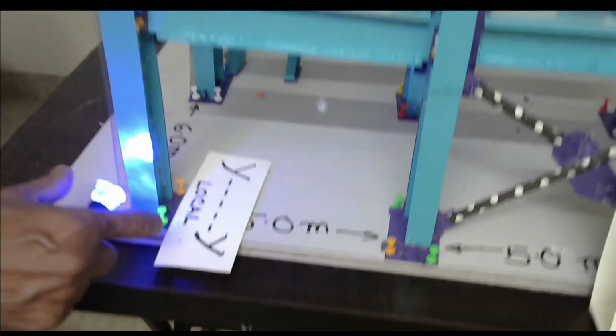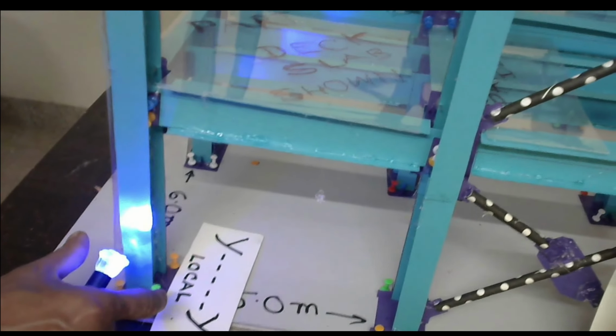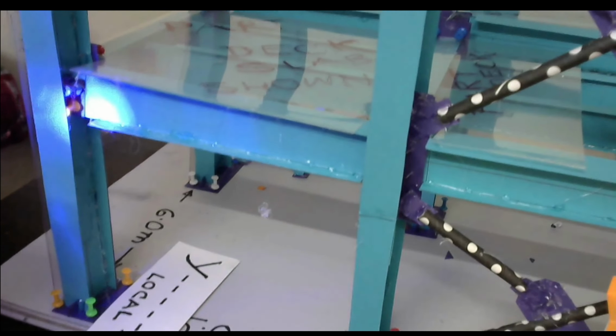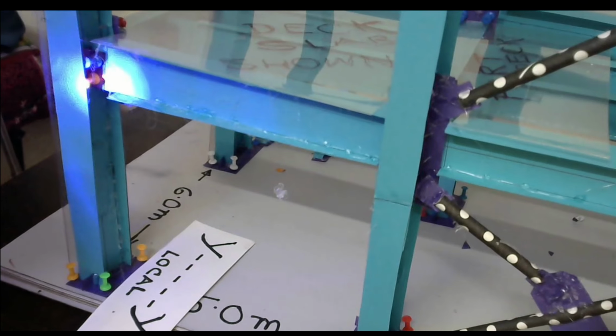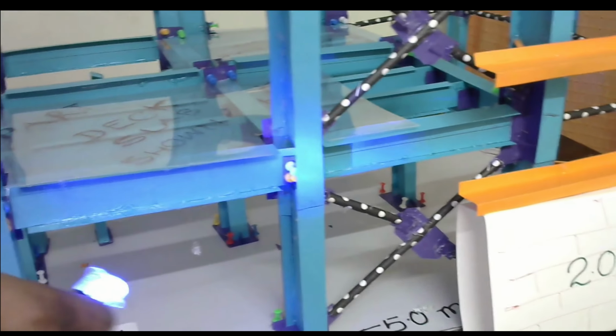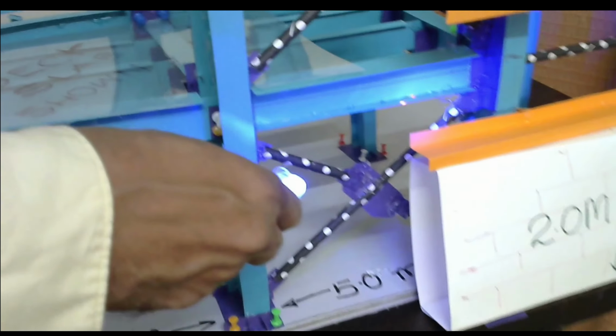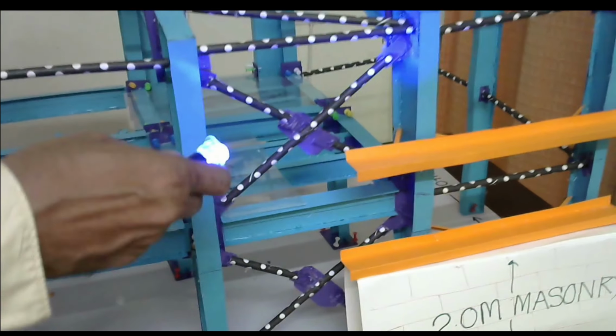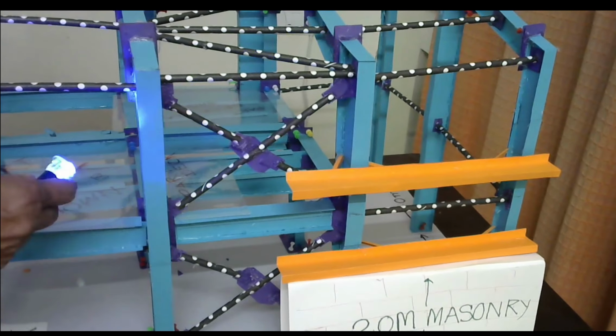So about the YY axis, at the base plate the joint is hinged, and then coming to the top, you can see there is a cleat connection here. So this is a simple connection, so this is also a hinge. Okay, now again let us go along this beam. There is a brace here, cross bracing. So this is a non-sway frame, as I have already discussed what is a sway frame and non-sway frame.